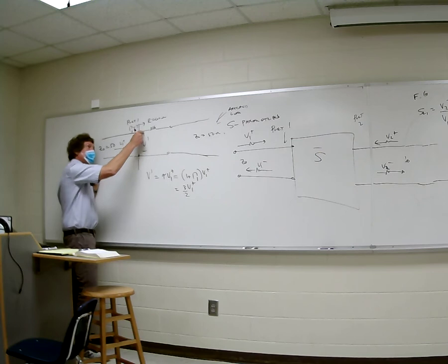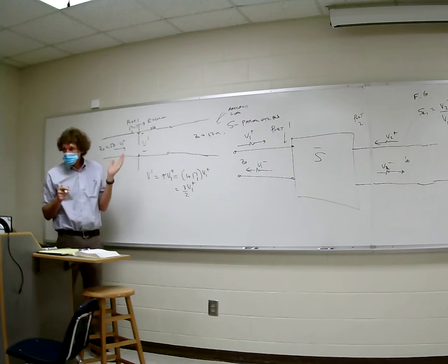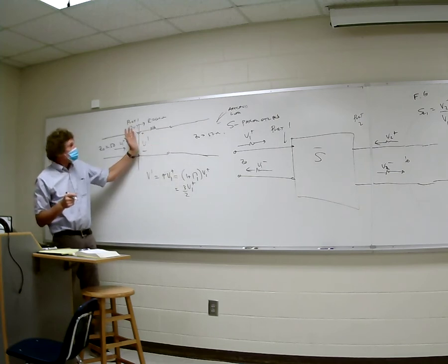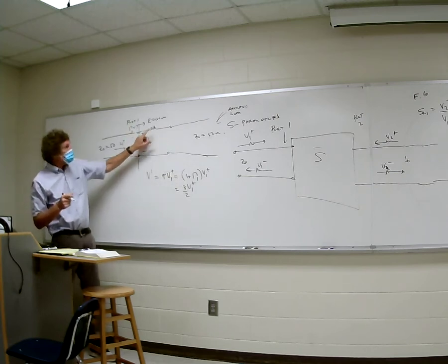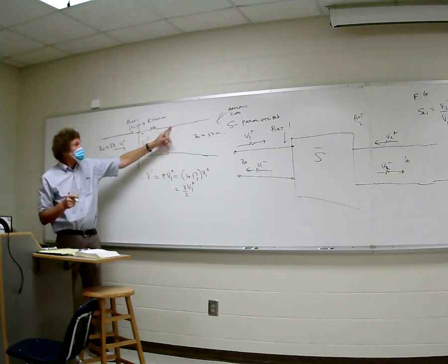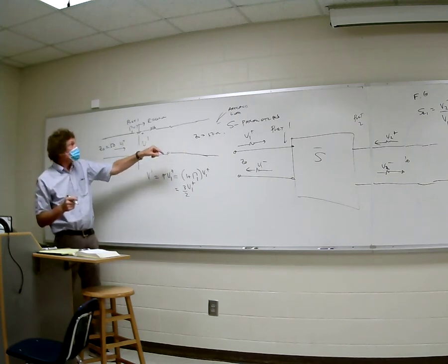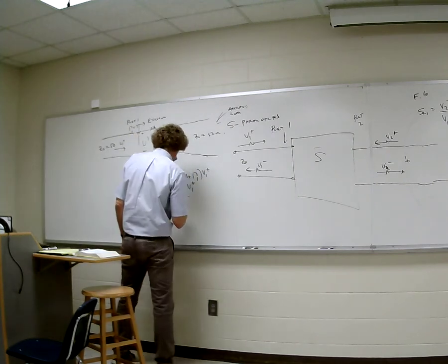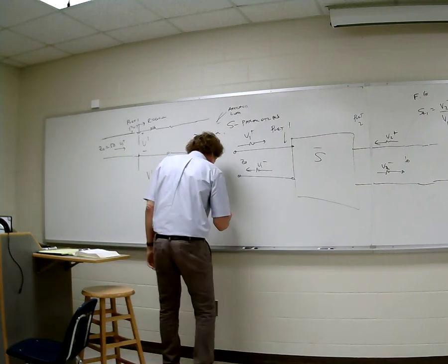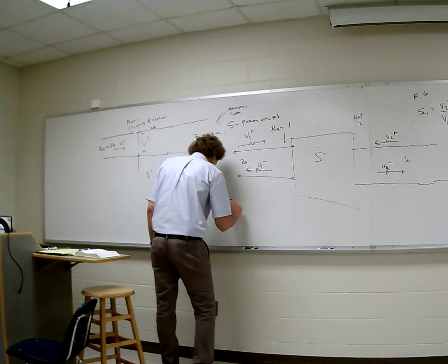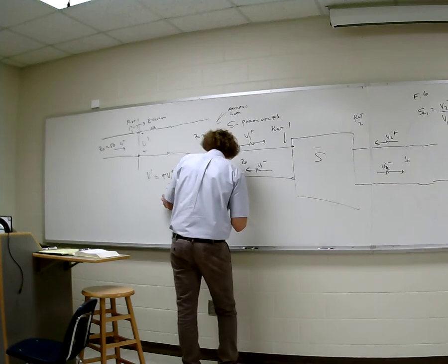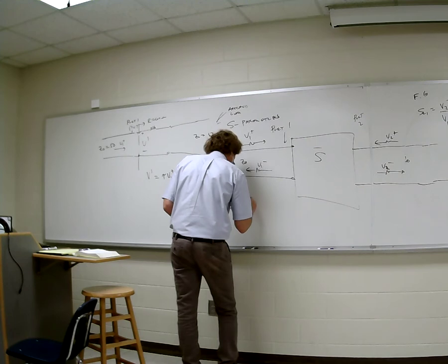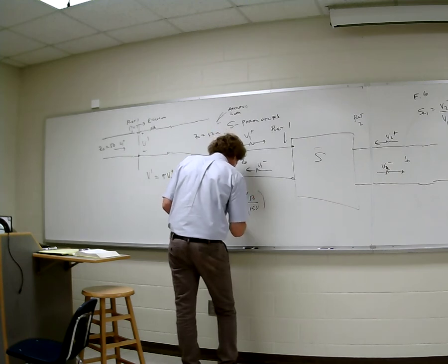Here's the transmission line. Now we're on the side where there's no transmission line. But that's not the voltage that gets out. We have voltage division, don't we? Because there's 100 ohms in series with 50 ohms. The amount of voltage here will be 50 over 100 plus 50 times that incoming voltage. So then, that's my V prime. Now I can say that my V2 minus would actually be equal to this voltage here, V prime, times 50 over 150, or 1/3.